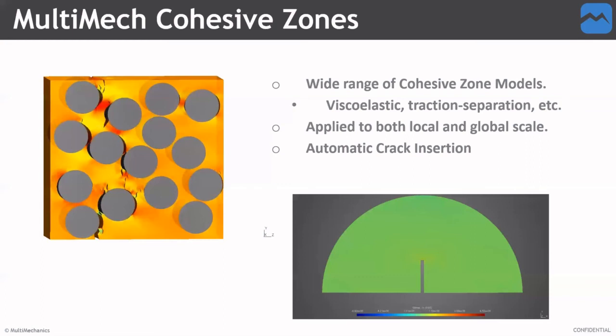Yeah. So with the unidirectional carbon fiber microstructure, yes, we can model thin surfaces. Exactly how thin is up to the user. So we can see here we have an interphase region, and this is just a modeling technique we use for continuous fiber composites. We have a thin layer here, and we represent this by different properties, for example, different damage parameters, failure, etc. on this area. You can make this thinner.